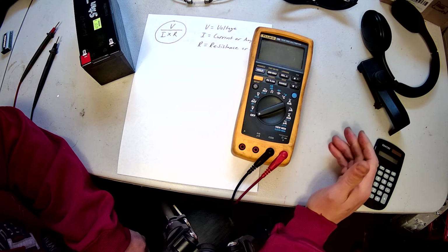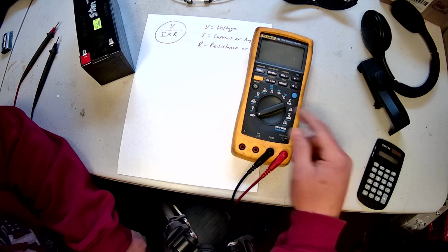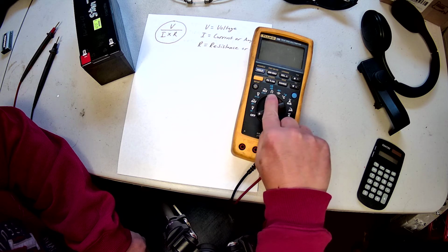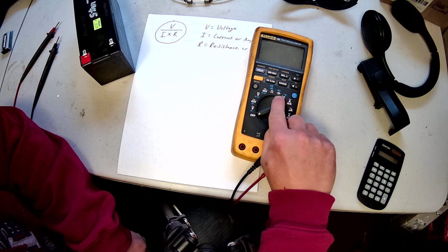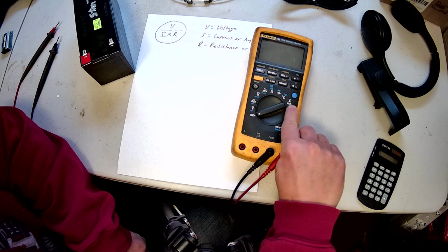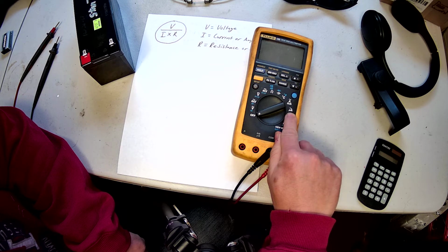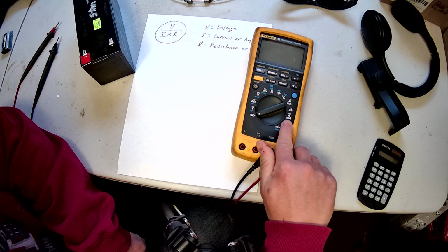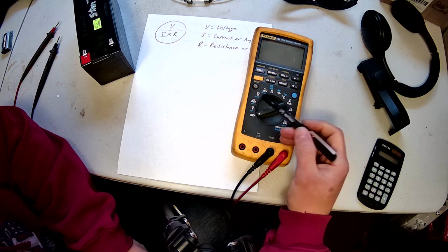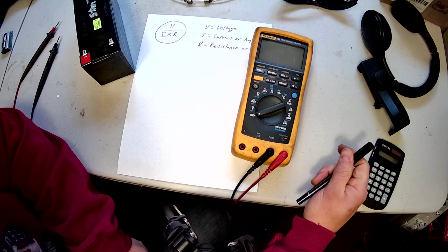But when we're working with any type of a battery, anytime you store power, it's going to be DC power. So right here I have voltage DC, millivolts DC. Here's the ohm symbol for resistance. This is for diodes. This is for measuring temperature. This is for measuring amperage AC. This is for measuring capacitors. This is for measuring amperage in DC. So the main things we're going to use right here is we're going to use the voltage DC and the amperage DC for the experiment that we're doing here.